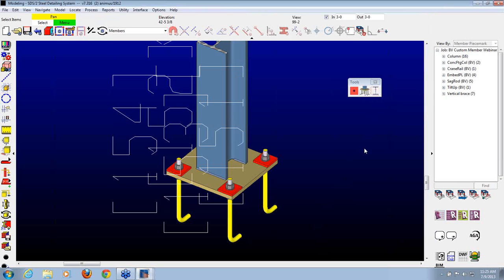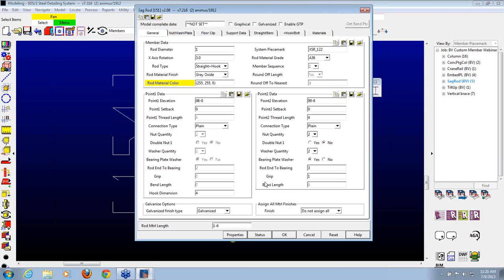There's one last thing that I want to go over here, which is coming down the road in 317. There's a Get The Point plugin. If you've noticed, there's a checkbox in some of these custom members that I haven't gone over. This checkbox is Enable GTP. Now what this does is it enables Get The Point, which allows you to get the specific location at the midpoint top of some specific members.